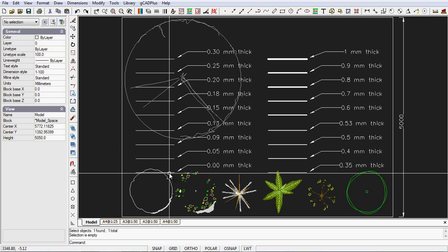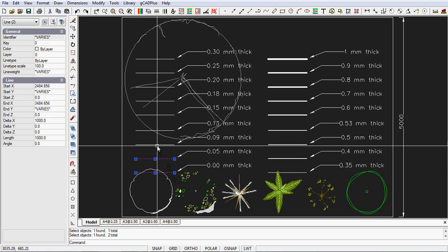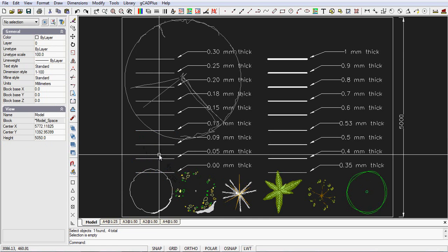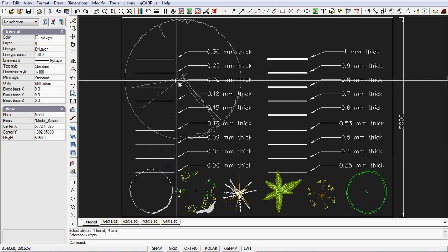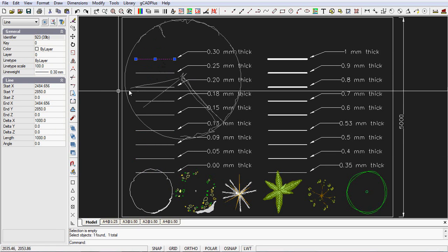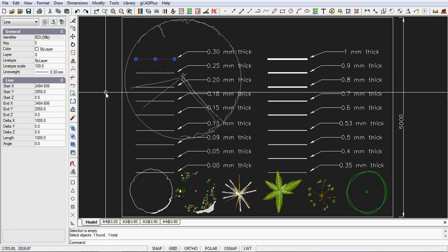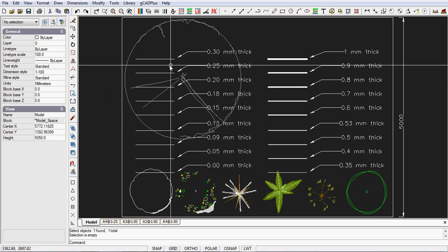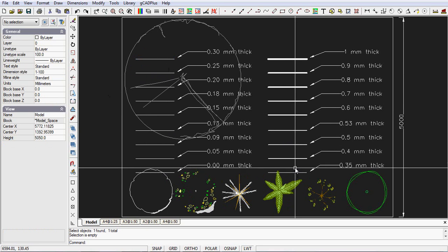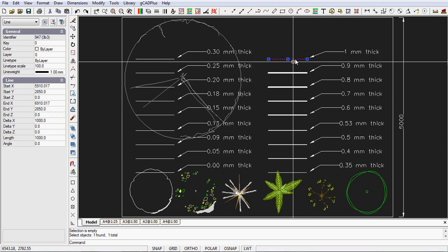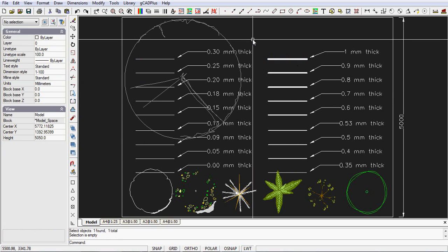And what I've done is to assign each of these 1 metre lines in this drawing a different line thickness. So if we move up to the top and I select this line, it's been set as a line weight of 0.3 of a millimetre. And the same would happen if you were working in inches. It'd be fractions of an inch. So this is a graded series of line types. If we come up here and click on this one, it's been set at 1 millimetre thick.